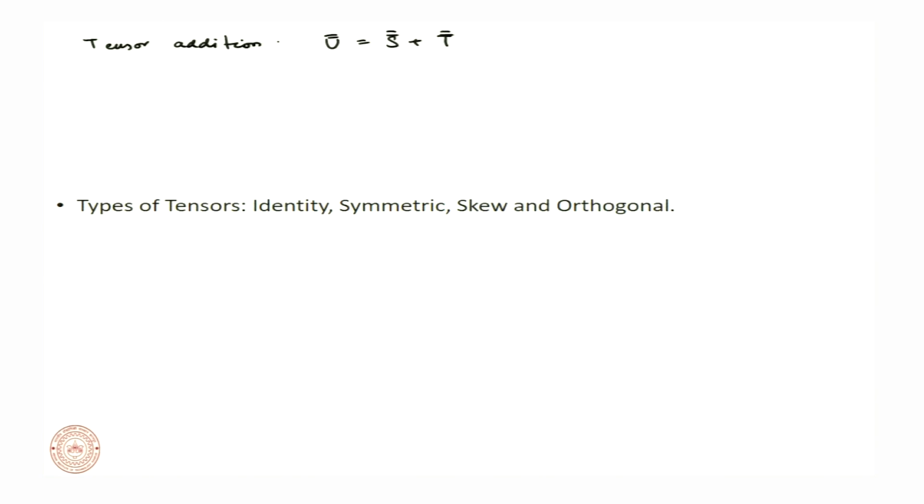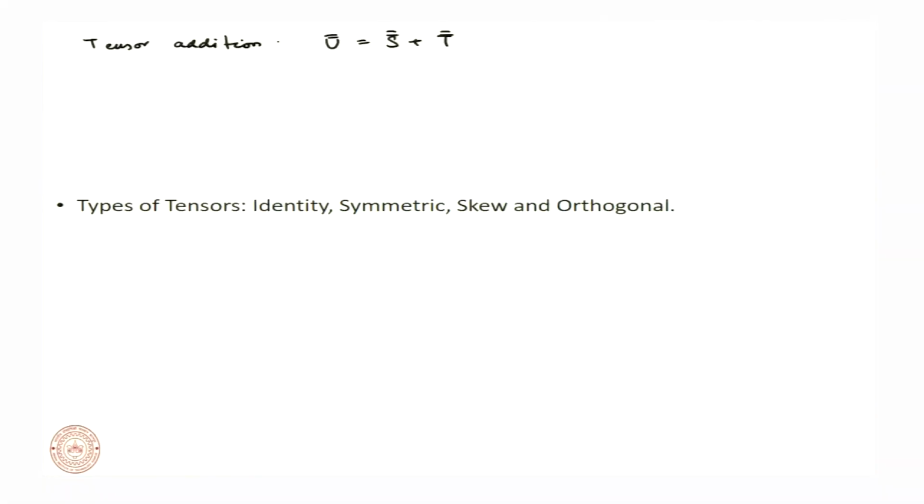Two tensors having the same units can be added together. For example, you could add two different directions of stresses into one stress, or split one stress tensor into two stresses. This is typically done in solid mechanics. You can separate out the shear component into one, and you can separate out the hydrostatic component into another. So deviatoric stresses can be broken, and the hydrostatic components can be taken out.